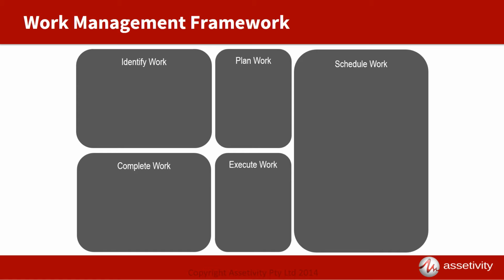In addition to these basic processes, we recognize 13 sub-processes that are required. We'll talk about these next, starting with those relevant to identifying work. The first step in identifying work is to establish all of the tasks that are competing for maintenance resources. This is done primarily by interrogating the organization's maintenance information systems, but often also involves consulting other sources, such as vibration analysis databases, project engineers, and structural engineers, all of whom may have special requirements.